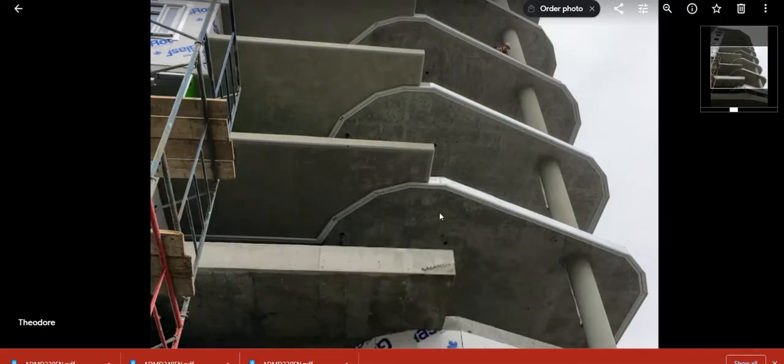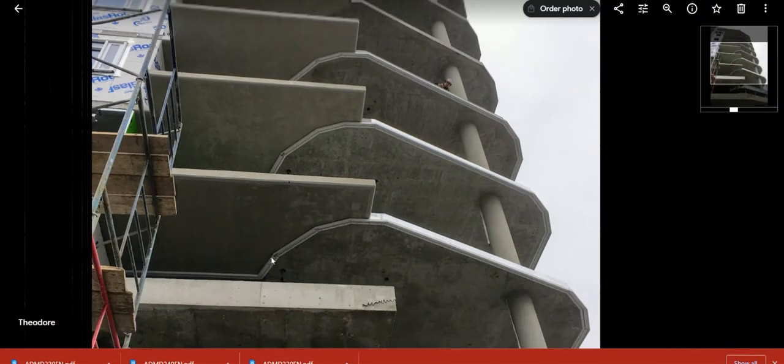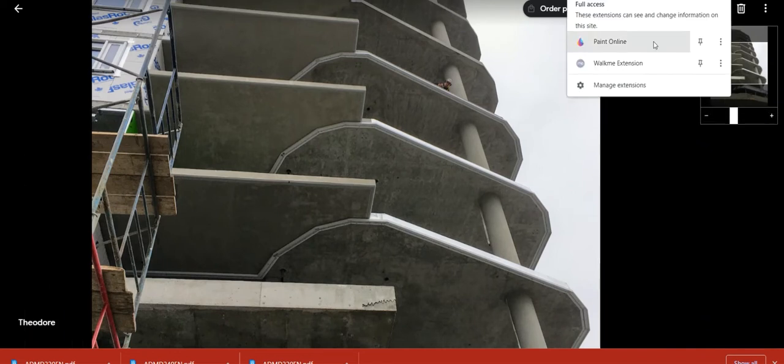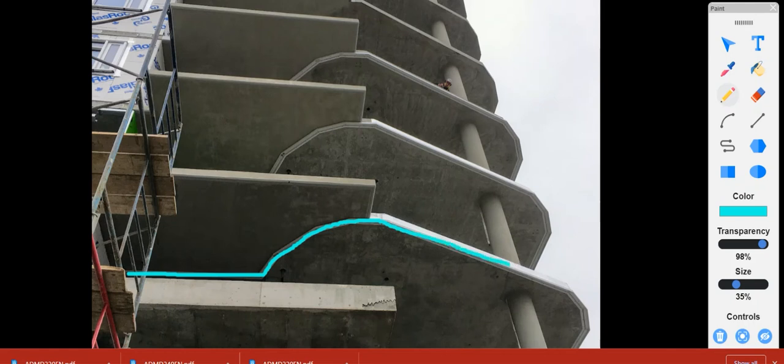And so here's a building where this is the actual top track being put in place for the window wall system. The glazing system is going to wrap around and go back into here, and there's going to be a balcony here, obviously. So your exterior wall is essentially reliant on those seals that go along that track in this window wall system. And oftentimes that goes around the entire building, and that's it.